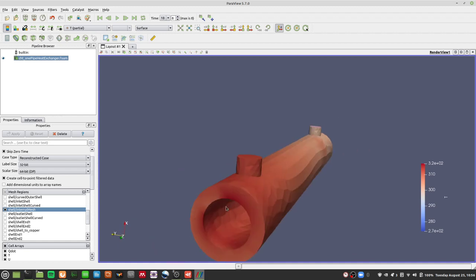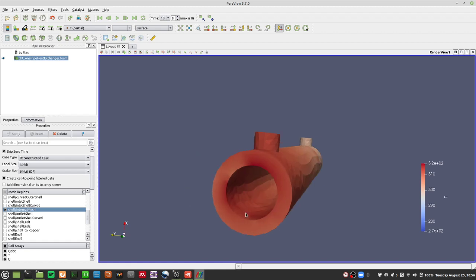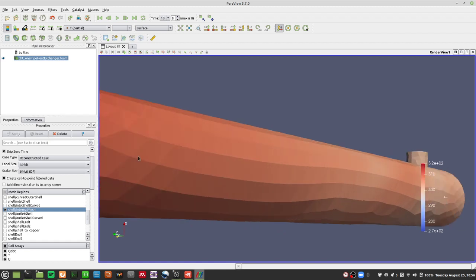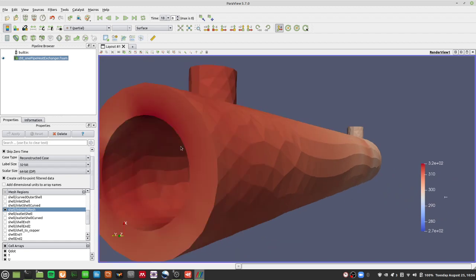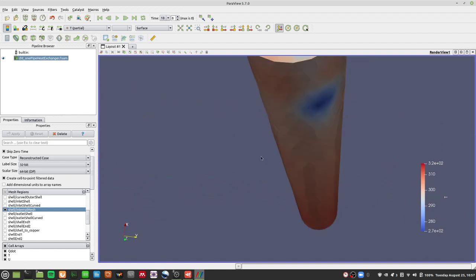Obviously, there seem to be some hot spots over here at the end of the tube. That's normal because the fluid kind of gets stuck there, so it's not really doing much in terms of getting heat out. So this is okay-ish but not a very good design in terms of efficiency, possibly due to fluid being stuck here towards the end, and it will be stagnant because there's no real reason to move around anywhere. But you can see that the shell side is heating up.